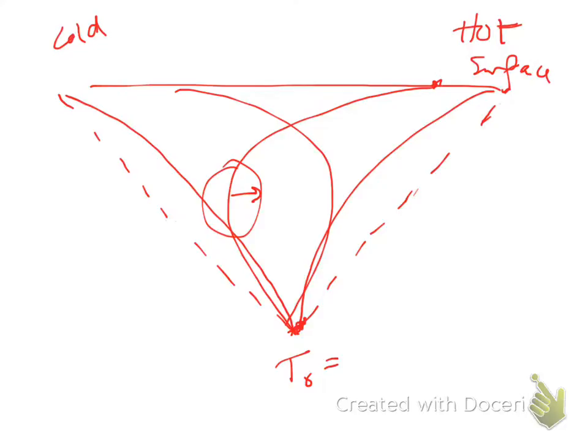There's a lag. So if you're down a certain depth, say a meter in Fairbanks, you could have a lag where you actually melt the ice at the beginning of winter instead of at the peak of summer, because it takes time for this to warm up down below. So it depends on your hot and your cold extremes compared to the temperature and how fast it's moving back and forth.